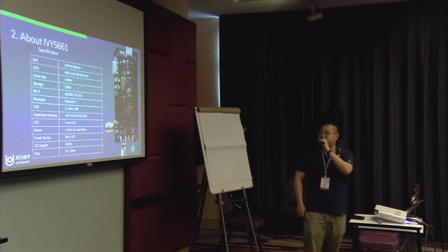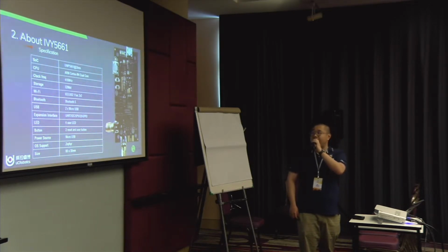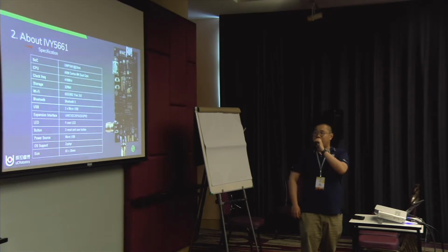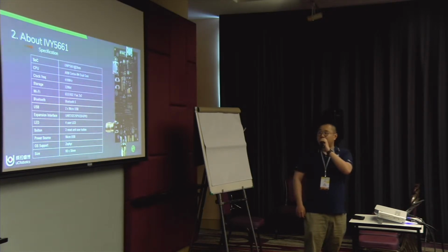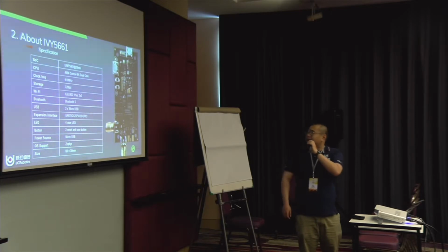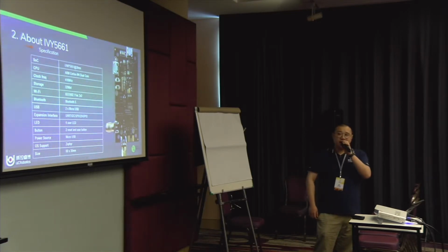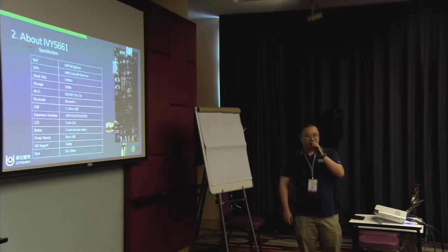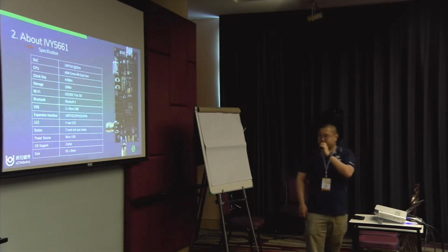Storage will be 32 megabit, and for the RF part, we support IEEE 802.11ac and Bluetooth 5. And as IE spec, we have expansion interfaces which support UART, I2C, SPI, I2S, GPIO, and the operating system on this board is Zephyr.